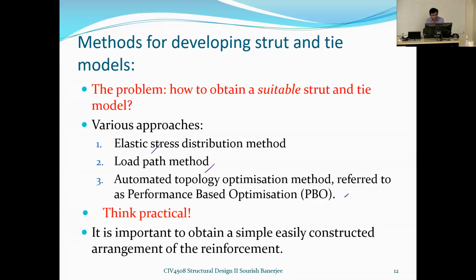Now I've said think practical. Think practical means it is very important to think about what you can practically implement, not just something which is not practically feasible. It is important to obtain a simple, easily constructed arrangement of the reinforcement. This is very important because the more complexity you introduce in your design, the more problems there will be while constructing those structures. And sometimes you will find that instead of cost saving, it can actually incur more cost when you construct them. So let's look at the approaches one by one.